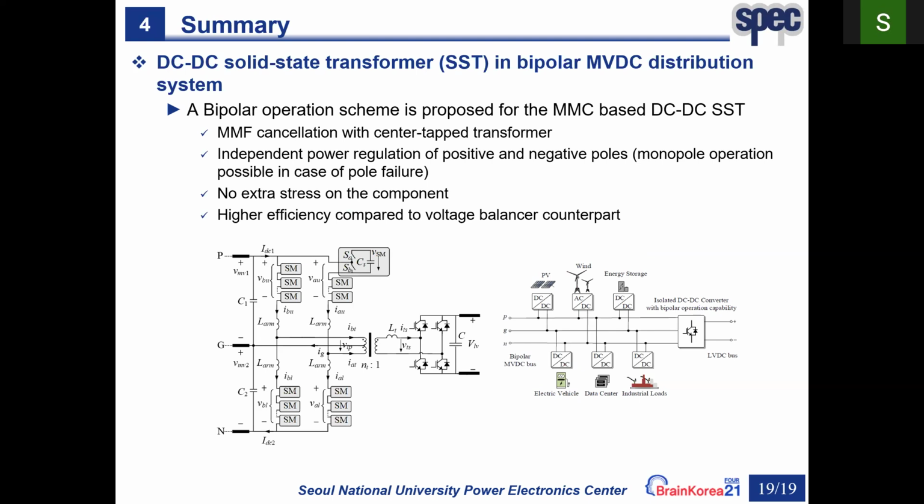The independent power regulation of positive and negative poles, as well as the monopole operation, can be realized, and no extra stress on the components is added. Since no additional power converters and components are required, this method assures higher efficiency compared to the voltage balancer counterpart.